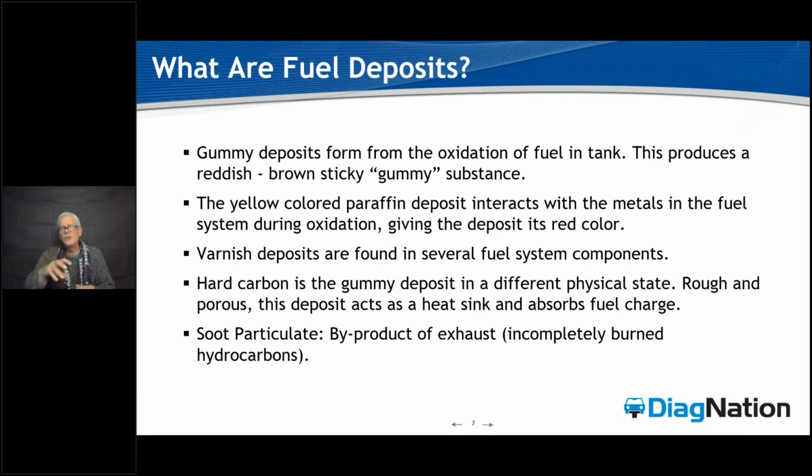And once you really start to get a picture of this, then one can understand why the short trip cars, the short trippers as I call them, are getting in real trouble, because they are not getting the time, the heat, and the mileage to burn these fuel and oil carbons out. They're just sitting there stacking up in a very close tolerance engine.